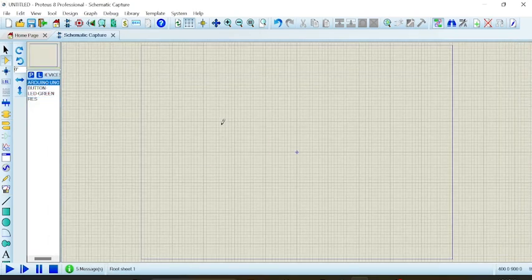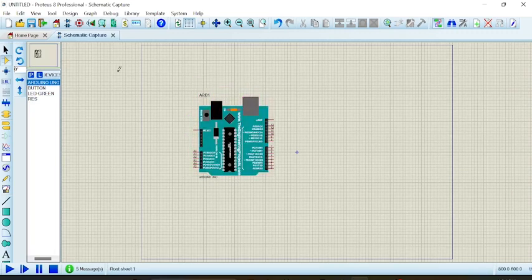Input the various devices into the workspace, the Arduino, the LED. Let's connect the LED to pin 1 of our microcontroller. You can use any pin. Sorry, never connect the LED directly. Always use a protective resistor in order to limit the amount of current flowing to the LED. This is because the LED is driven by current, and a high amount of current will destroy the LED.